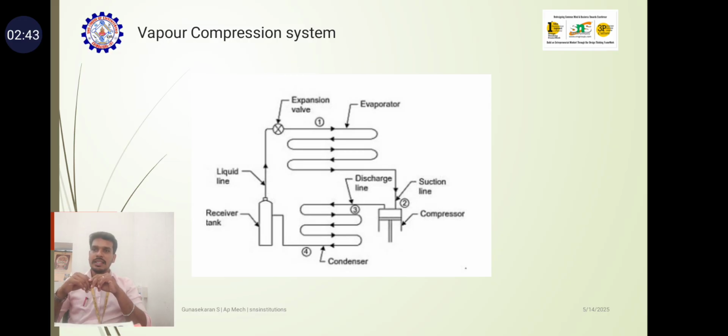This heat exchange occurs without changing the pressure and transforms the refrigerant from gas to liquid state. The condenser can be air cooled, water cooled or evaporative, depending on the system design. The main purpose is to prepare the refrigerant for expansion and cooling by removing heat absorbed in the evaporator.